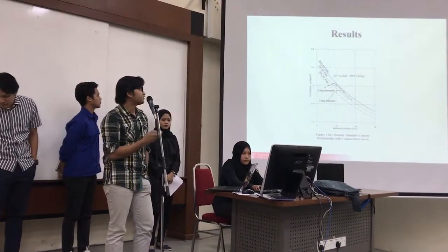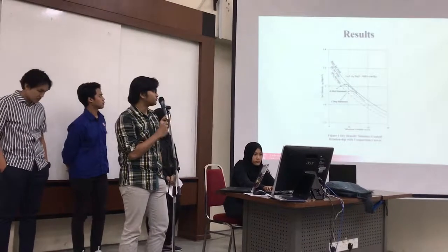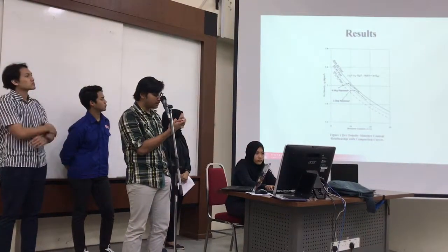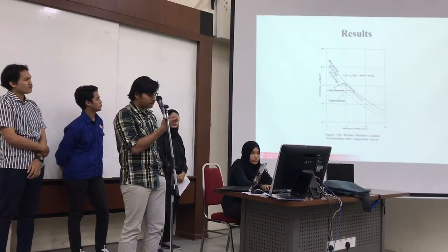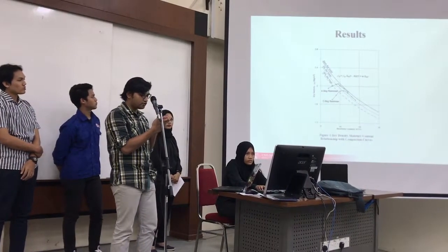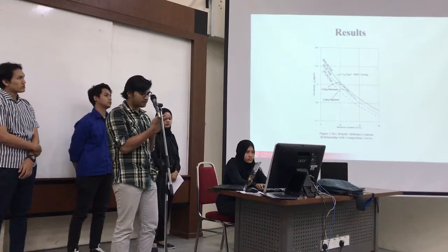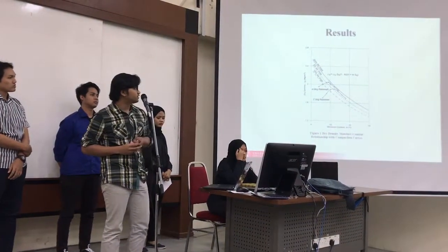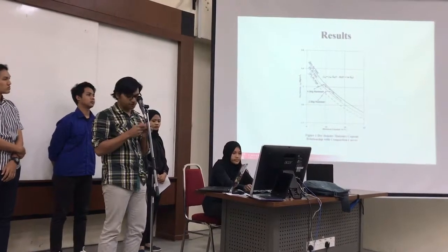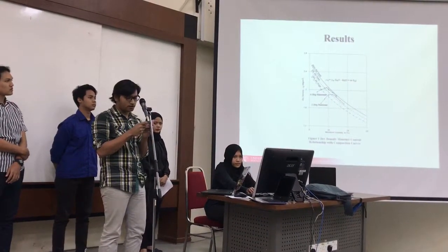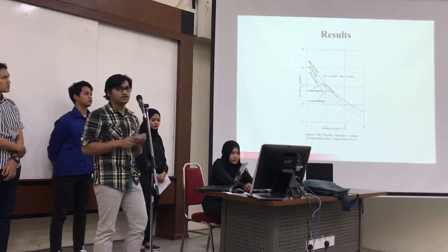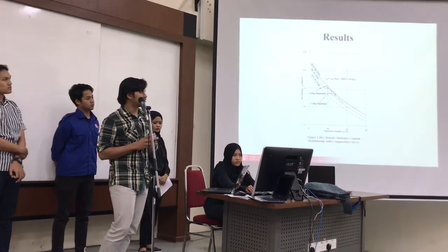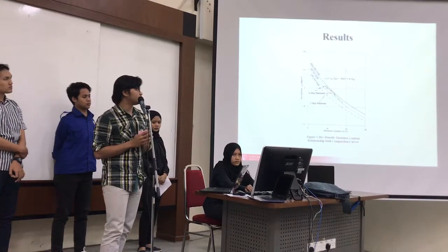Zero air void: by referring to the graph, we can also find the zero air void line. The zero air void line indicates a completely saturated soil mass, and no part of the compaction curve can be beyond the zero air void line. But achieving this state is too costly and time consuming, as it requires removing all air voids to reach a fully saturated condition. Furthermore, there is no engineering equipment that can achieve this state.